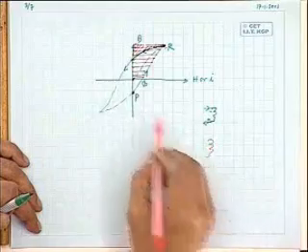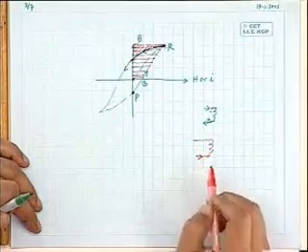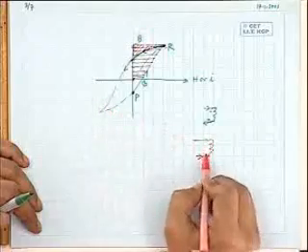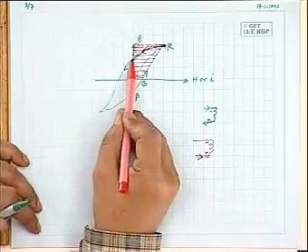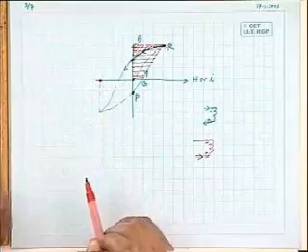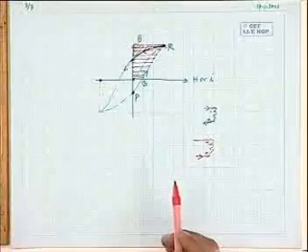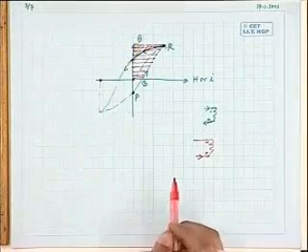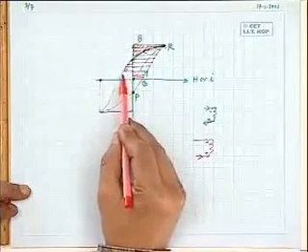In the second case, the current is totally negative, that is this zone, from this to this. Current is totally negative, meaning current is entering through the other terminal. And what about dB dt? It is negative, so this side plus, this side minus. So when current once again starts building up from 0 to minus I max, what will happen to the energy? Will it be an absorption of energy? Absorption, because through the plus terminal current is pumped into the coil. And what will be the magnitude of that area? This will be H dB, once again this area, this whole area.